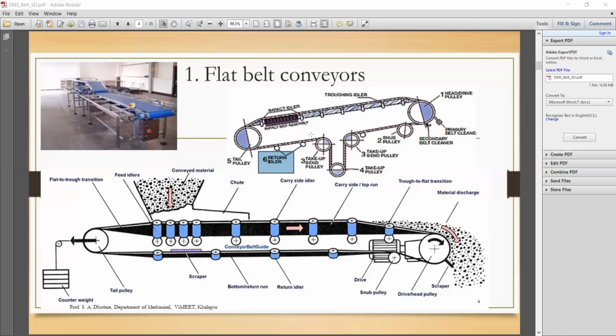It can affect their strength, so that's why we normally avoid using a flat belt drive in high temperature segments. There is always a possibility of slip as stretching occurs due to heavy load. So in that context we use a take up pulley to take care of that, but it has some limitations also.